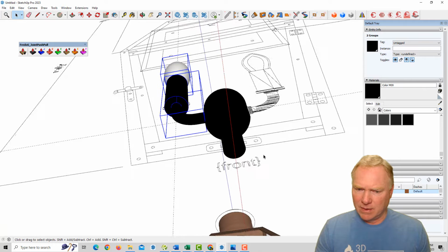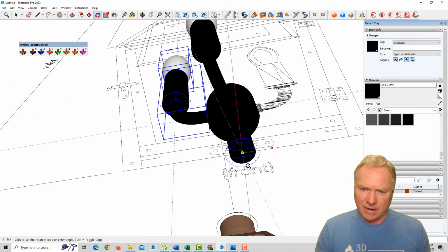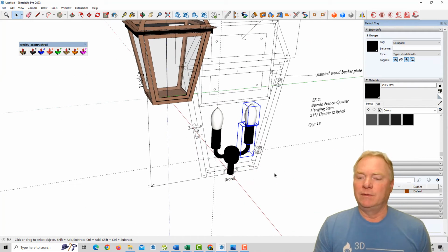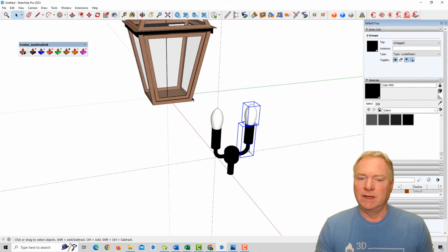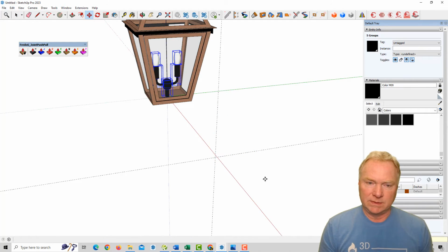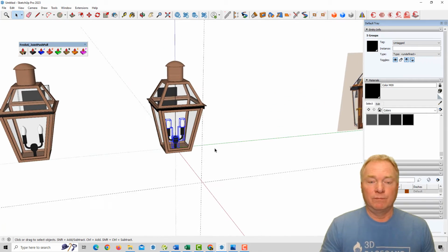All right, and then I'm going to take the side piece here in the bulb, and let me cut the 2D back on. I'm going to rotate those, Q, select right in the center, hit the control key to make a plus happen there for a modifier. That I'm going to come around 180 degrees, and I've got those two pieces. I'm going to cut off the 2D again. I'm going to select these guys and move all of that back 24 inches. And now I've got my light fixture looking pretty good.